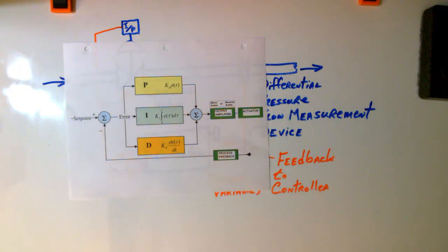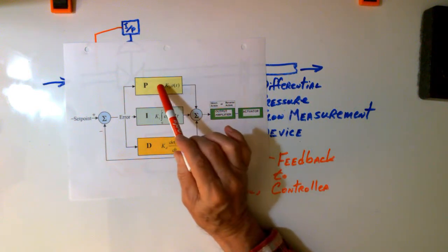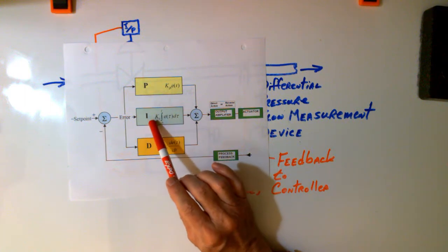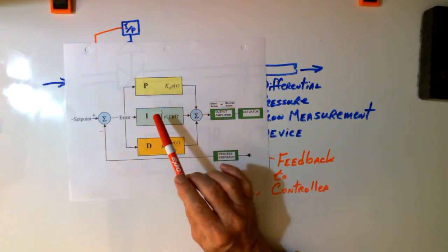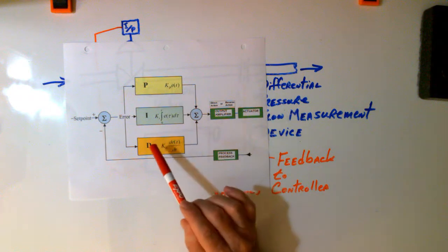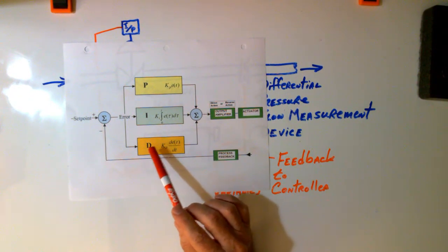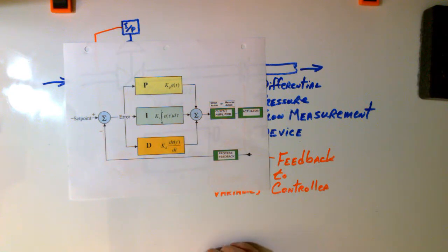Now then, this controller, I'm going to say at this point, is a PID controller, which means we do a multiplication and we do a mathematical integration. The I stands for integration, P stands for proportion, and D stands for derivative or differential. We'll ignore the D for right now, because we're not working with a system that really requires that math function.